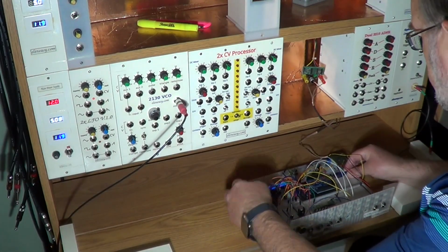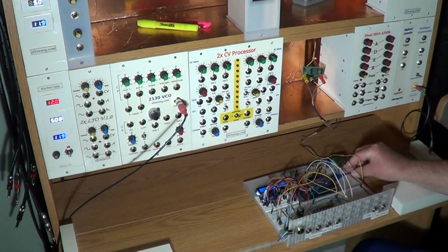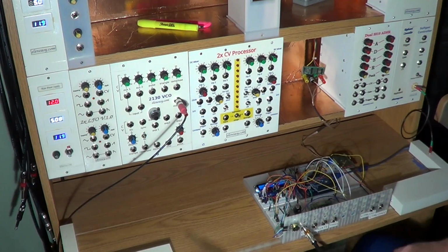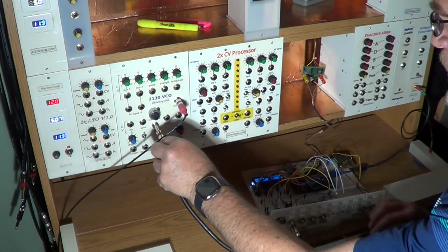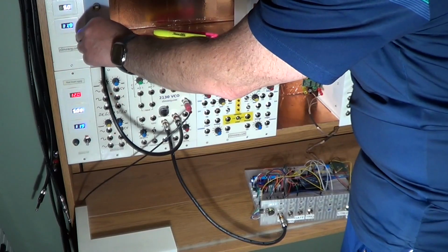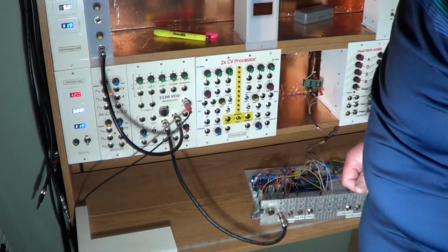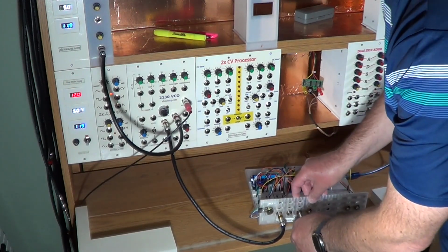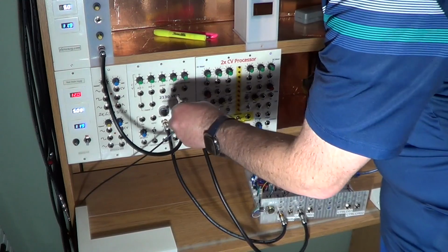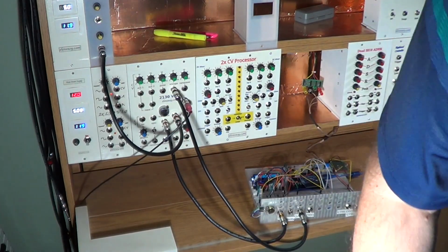First of all, the USB cable from the MIDI keyboard. Then the CV output of the module to the VCO input to control the frequency of the oscillator. Let's also add to the VCO input a steady voltage to adjust the octave at which we want to play. Now we need to connect the gate signal to the control input of the VCA embedded in the VCO, so we will hear the sound only when a key is actually pressed.